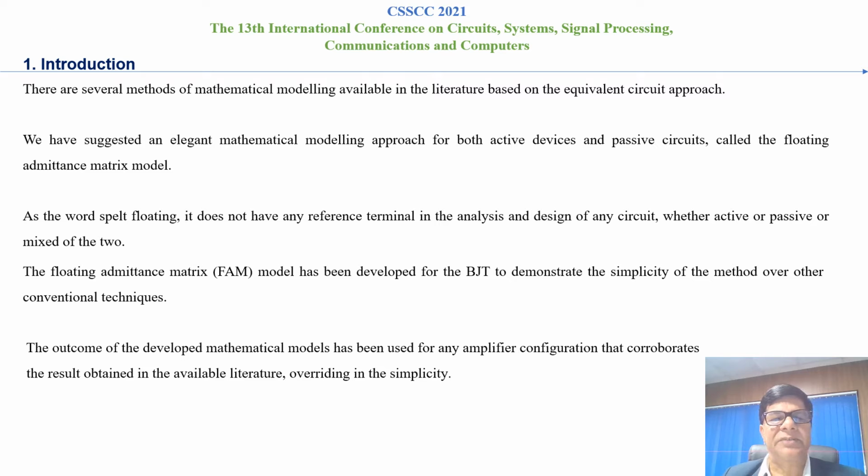The floating admittance matrix model has been developed for the BJT to demonstrate the simplicity of the method over other conventional techniques. The outcome of the developed mathematical model has been used for any amplifier configuration and corroborates the results obtained in the available literature, while being simpler.